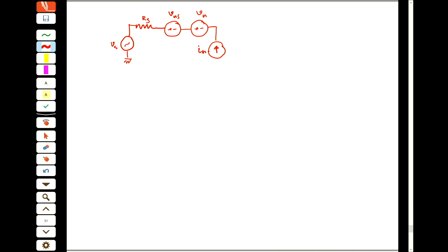and then the IN, okay, and then the small signal model of the BJT. This is R pi, and here we have a gm VBE, okay, and this is I out, and here is ground. You can have ro at the output, but no matter.